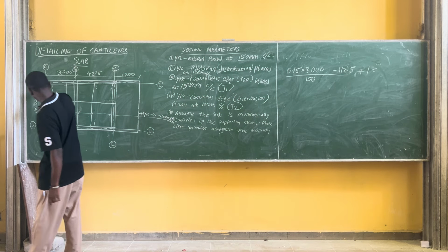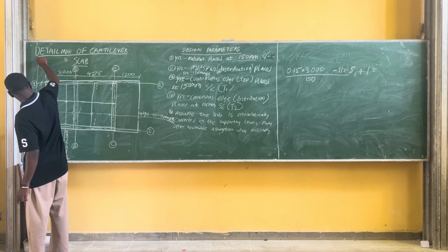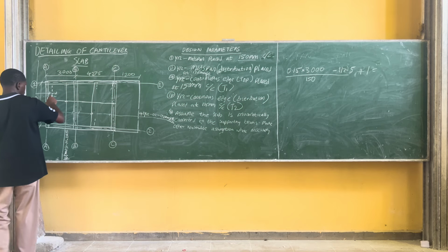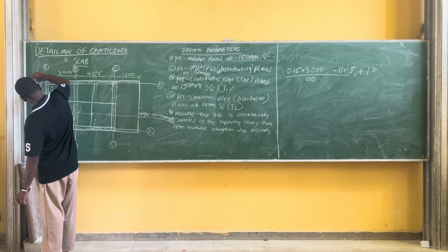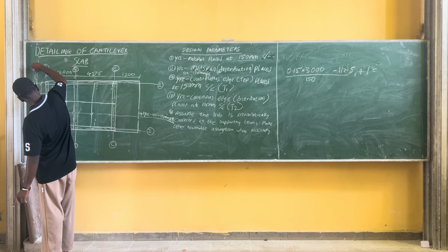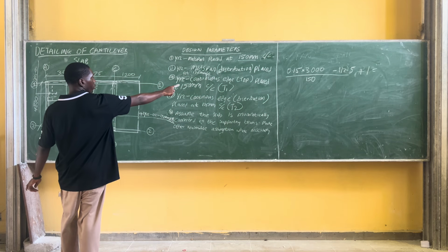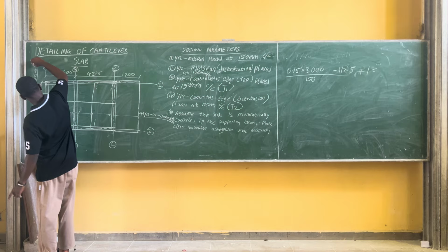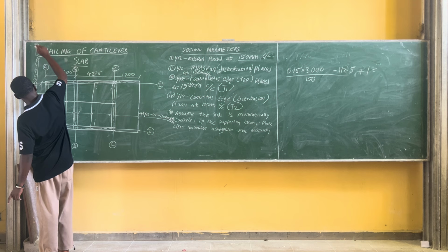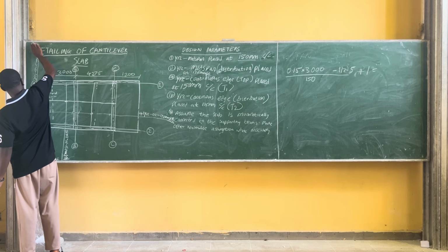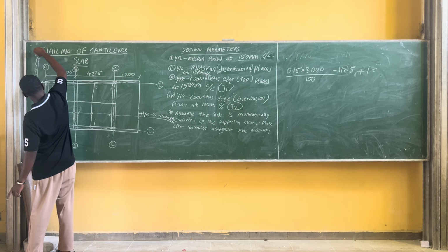Therefore, I'll put an indicator here, which is telling me that this reinforcement is spanning from here: 3Y12 bar mark 03 at this top reinforcement 150, 150 center to center, T1.